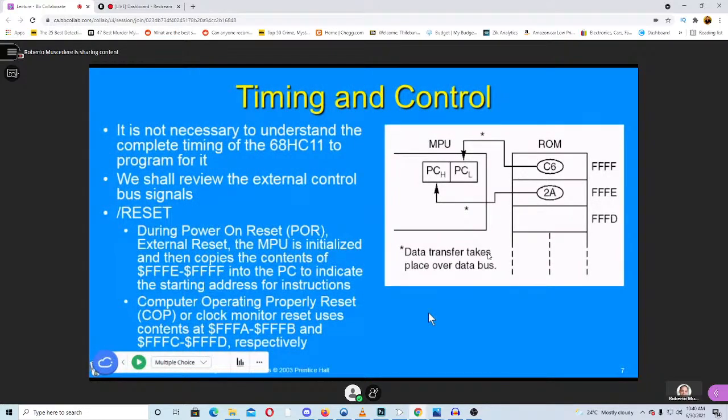What this is there for is to prevent the system from going out of control. What if there's a programming error and it starts running rogue code? What's going to make it go back to normal, right? So if we don't reset this timer, the system will automatically reset. Now, the reason it has a particular way of resetting the timer is because, what if you just have to write to one register, one place in memory, to reset this timer? Well, what if when the program goes out of control, it does that anyway, and does it frequently? Then this isn't very useful, right? So there's a particular process to follow.